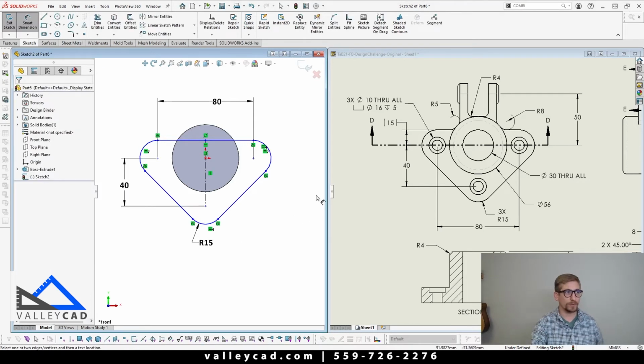Now you will notice in my drawing here that I have a 15 millimeter dimension, but it has parentheses around it. I know in the print or the picture that I had, it did not have that, but what the bracket stands for is it says reference. Now, why did I put a reference dimension there? Well, this is speccing off for our radius callout, which I'm already calling out right here.